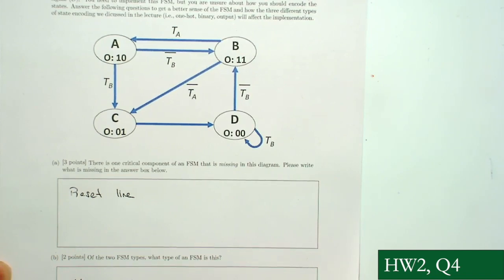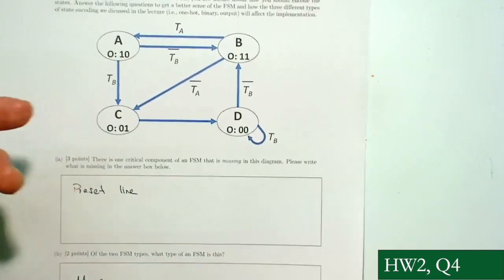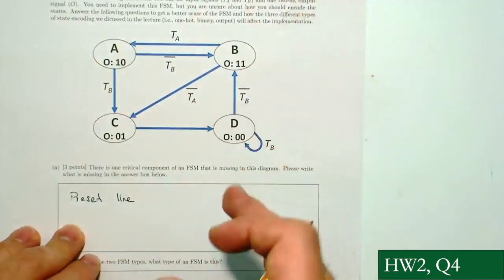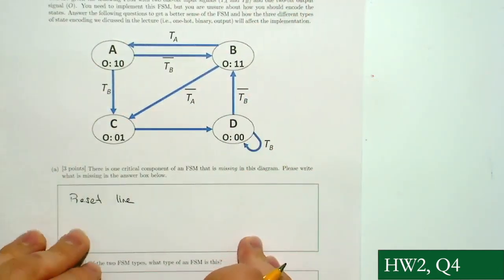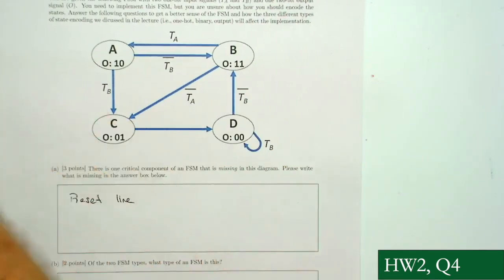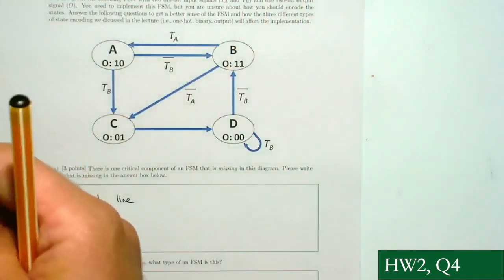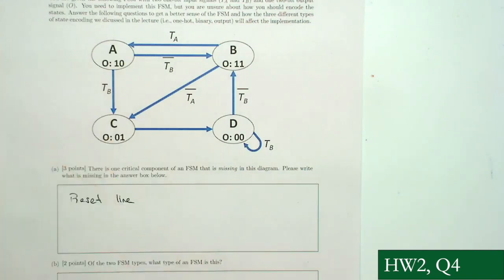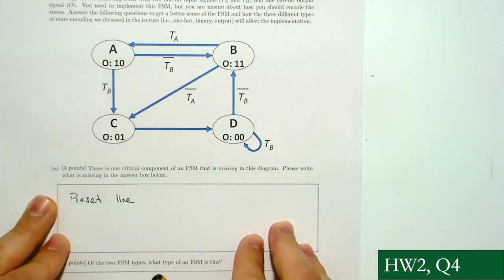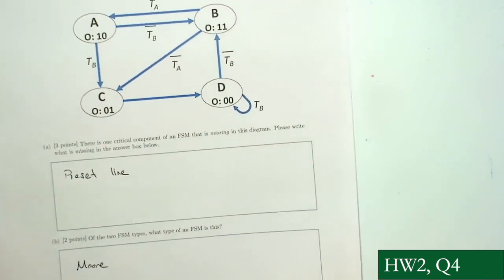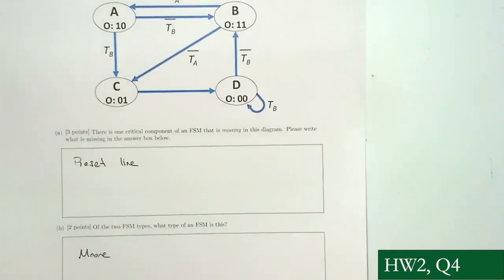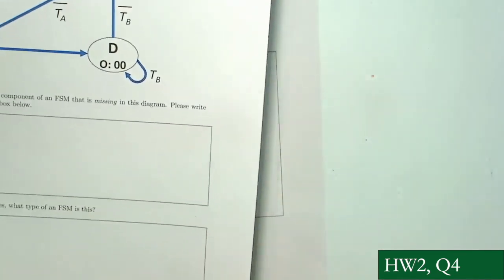So for the representation, you can say that this is our initial state, but to really have it as an initial state, you should make sure that when you start this FSM, it's really going to be the initial state. So how do you ensure that? You need to have some sort of reset line so that it goes there when you reset, and then you start it as an initial state. So basically, it means the same thing, to have the initial state and the reset line. Okay. Any questions related to those?